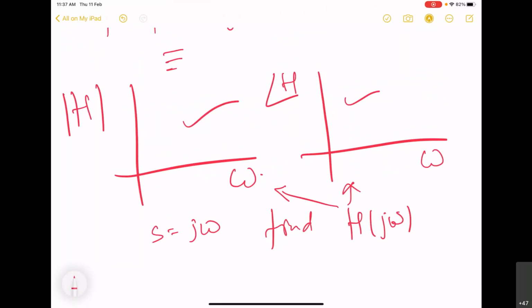And the plot should be sufficiently accurate. It need not be 100% accurate, so that we can take its help to fulfill our desired design specification. For example, for the common source amplifier example that we discussed just now, if you have the approximate plot for the voltage gain, you can see how much gain you will get at a certain frequency. If it fulfills your requirement, then fine. Otherwise, you will try to do the modification.